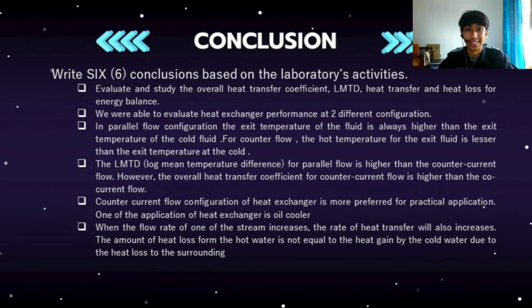Our conclusion for this laboratory activity: we evaluated and studied the overall heat transfer coefficient, log mean temperature difference (LMTD), heat transfer and heat loss for energy balance. We were able to evaluate heat exchanger performance in two different configurations. In parallel flow, the exit temperature of the hot fluid is always higher than the exit temperature of the cold fluid. For counterflow, the exit temperature of the hot fluid is lower than the exit temperature of the cold.